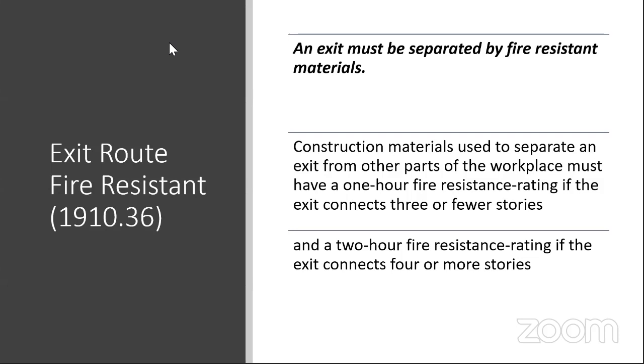Good. Okay. So the summary for emergency exit. The first thing is, what is an exit? An exit is the path which contains three parts: exit access, exit itself, and exit discharge. Whatever the part, it should always be free from any kind of obstruction. It shall be unobstructed, right?